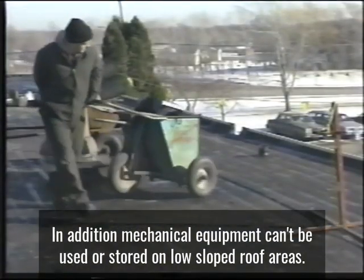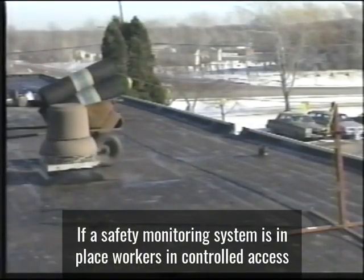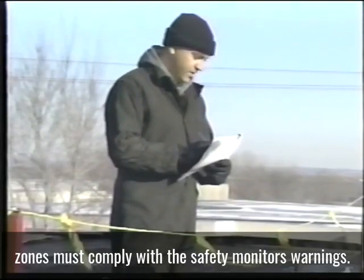In addition, mechanical equipment can't be used or stored on low-sloped roof areas if a safety monitoring system is in place. Workers in controlled access zones must comply with the safety monitor's warnings.